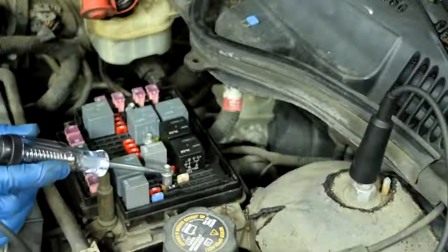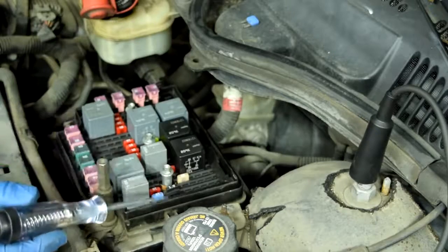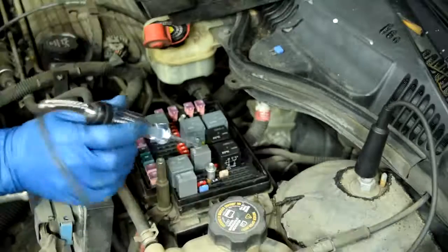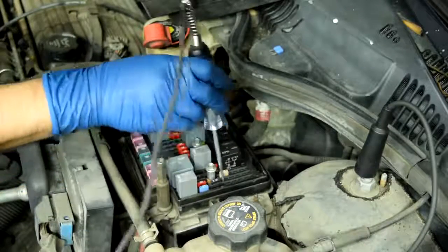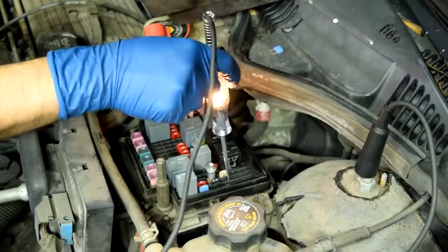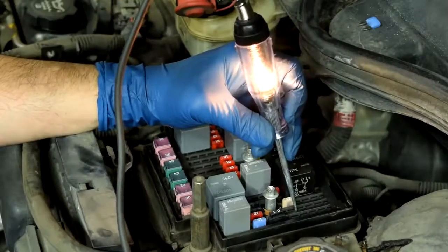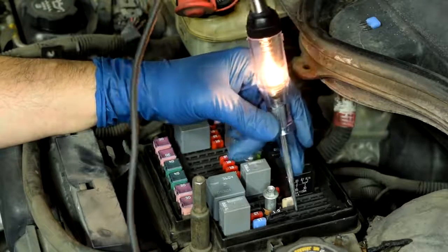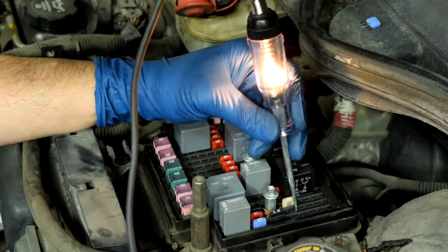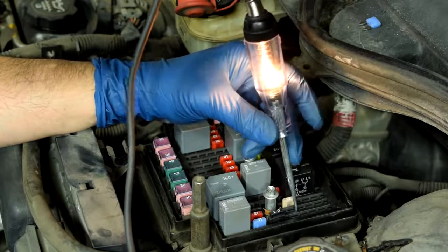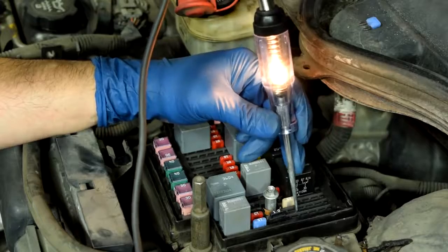Alright, since the wire to one of these pins for your fuse is connected to the battery, all you have to do is to get your test light connected to ground, and then test the 2 pins where your fuse goes. And the one that gives you a light, that's the one that's coming from your battery. So there, not only we found out which pin is connected to the wire that's bringing power from the battery, but since this test light is lit, this means that we don't have an open in that wire, but also we have good wire integrity. I'll explain that a little bit later in this video.